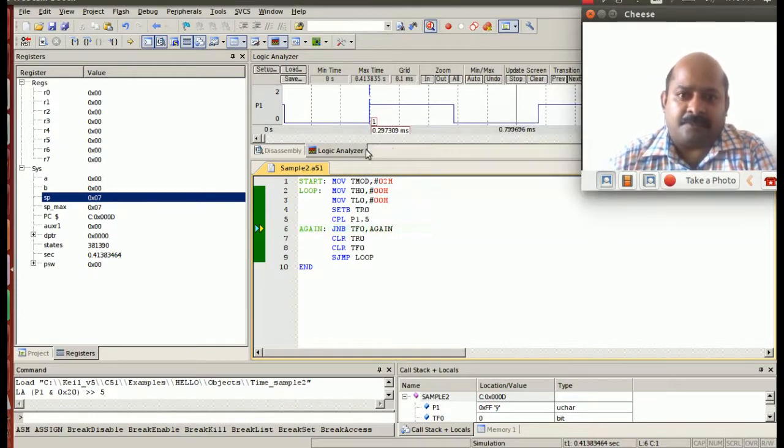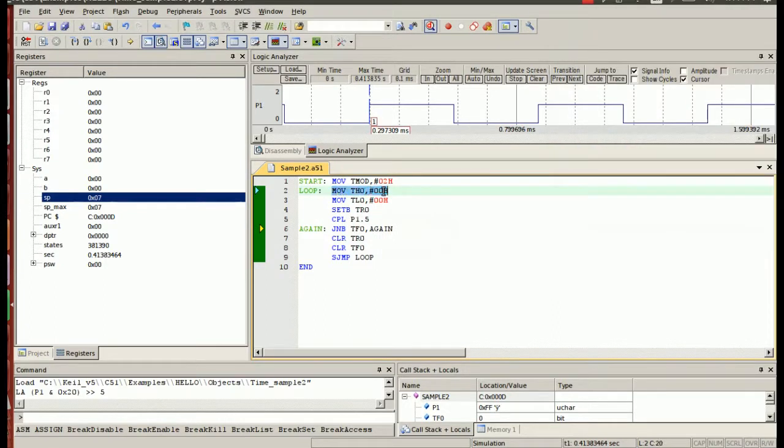The reason for this is whenever the timer count becomes very less, at that point the delay due to the instructions present in the program becomes significant. That means even though the timer is offering a delay, each of the instructions in the program also offers some machine cycle delay. So when the timer count is less, the delay offered by each of the instructions becomes significant. That is the reason why you see the deviation of the calculated versus the actual value.